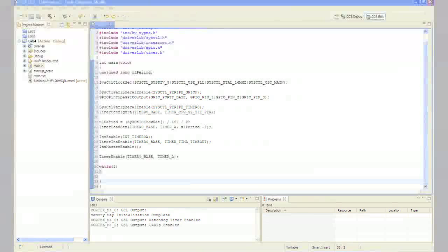In the interrupt handler, we must first clear the interrupt source and then toggle the GPIO pin based on the current state. Just in case your last program left any of the LEDs on, the first GPIO pin write turns off all 3 LEDs. Writing a 4 to pin 2 lights the blue LED.